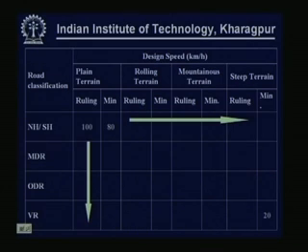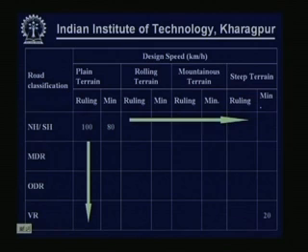That attempt should be made, but because of the terrain condition in a short stretch and also specific site condition, if it is felt that it is not really possible to achieve the speed, or it is not economical to construct a facility with a lot of investment to achieve that design speed, then we have another limit available with us, what is called the minimum design speed.